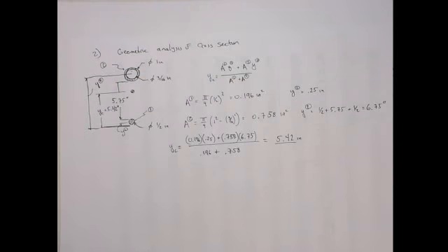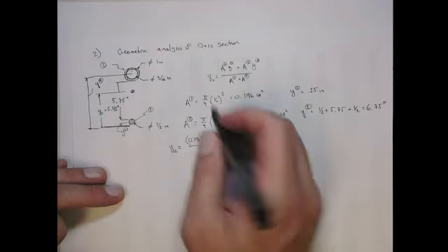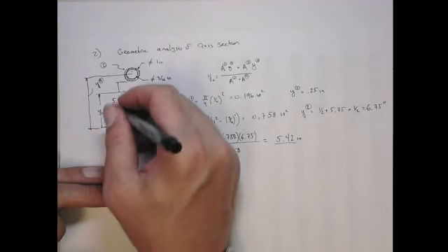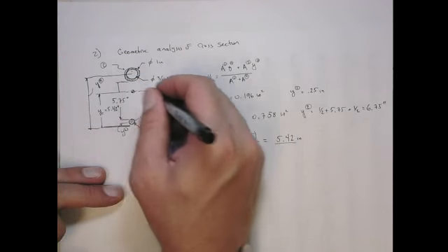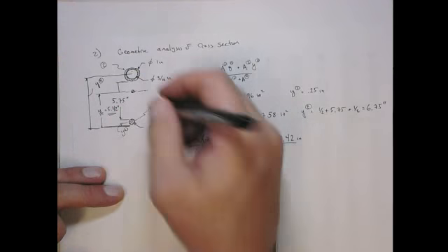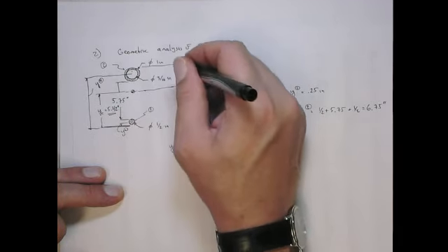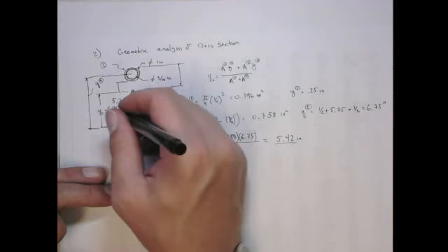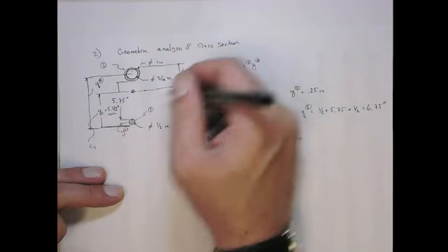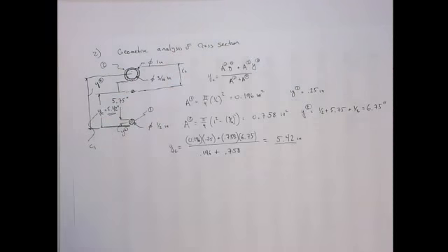Okay? So that means that this distance here from the neutral axis to this lower outer fiber is 5.24, and this distance to this outer fiber here, that would be the second C, right? This is actually the same as C1 and C2. Distance from the neutral axis to this outer fiber would be, let's figure that out.